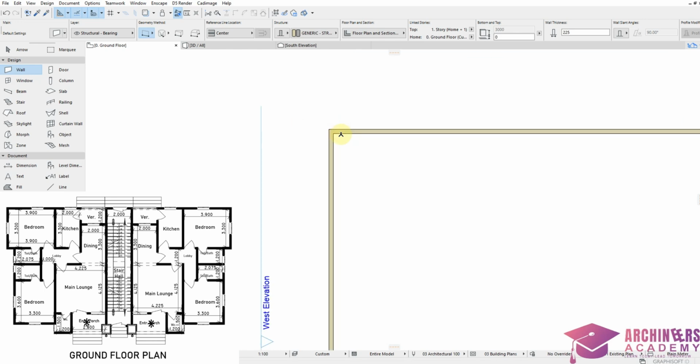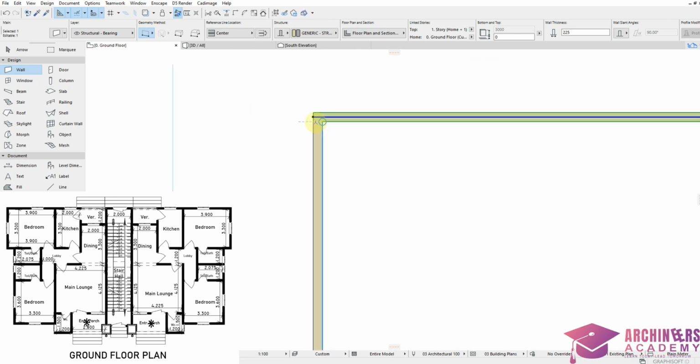So after doing that, then I have right here 3,300. Control Shift D, which is to duplicate a wall. If you don't know your Archicad shortkeys, go back to our previous videos on all Archicad shortkeys. We have over 60 of them. Learn them and they're very important. It helps you in accuracy, in speed, in proficiency, and lots more. So we have 3,300.